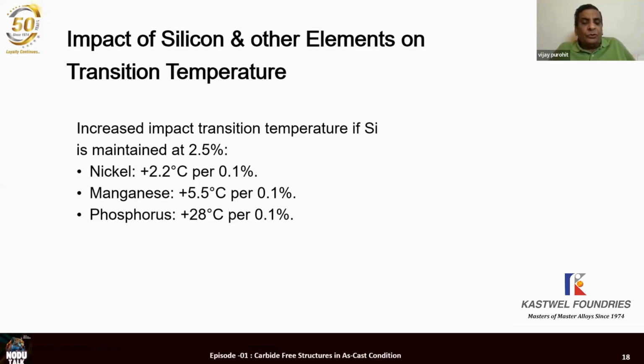And the composition of cold rolled controlled anneal scrap was very simple to understand. Remember, less than 0.1% carbon, less than 0.1% silicon, less than 0.1% manganese, less than 0.01% sulfur, less than 0.01% phosphorus. This was the CRCA scrap which was used for motor vehicle auto bodies.